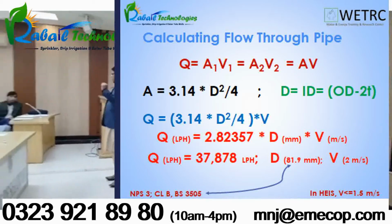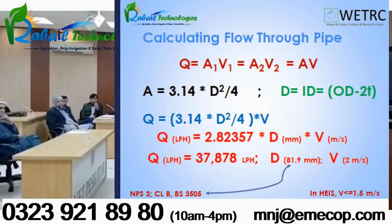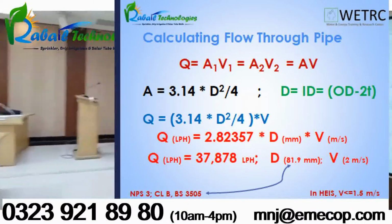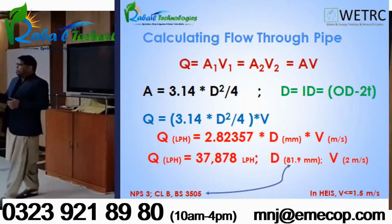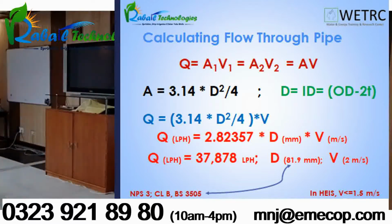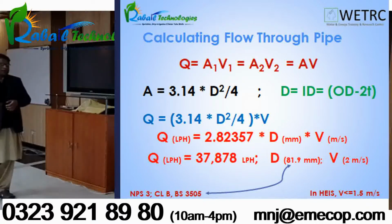Nominal, in common speech, right? And the thickness of that pipe is around 3.5 millimeter. So 88 minus 3.5 will give you around 82 or 81.9 millimeter. So the internal diameter is 81.9 millimeter, and the velocity that we maintain is 2 meter per second.